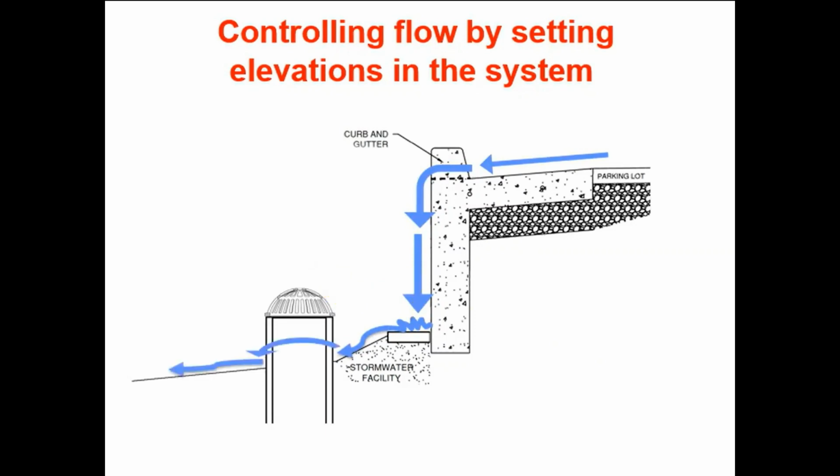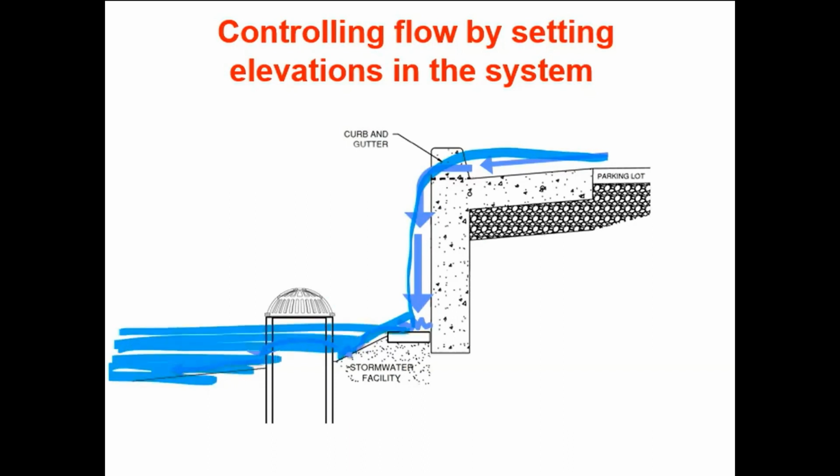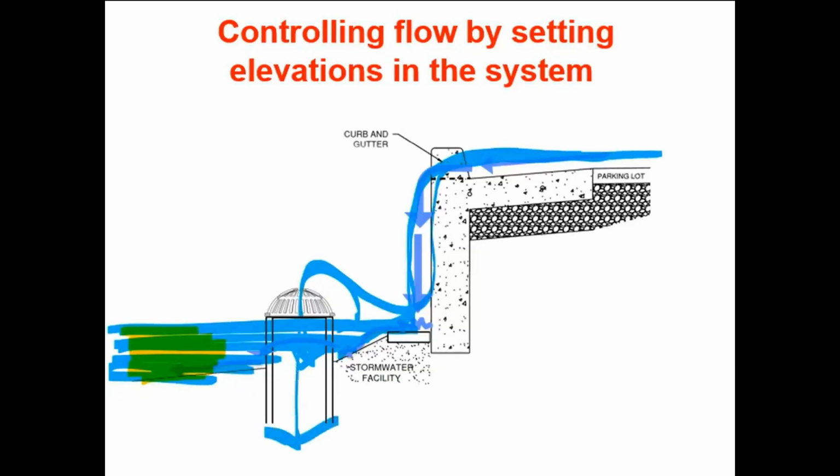The reason we want it at the top of the bioretention system is we want water to come down, hit the edge of the raised drop inlet. It's simply then going to go around the drop inlet. At that point, it's going to start to fill up with water. But because it is at the top of the bioretention system, any other water that comes in will go into the raised drop inlet. And so the polluted water that's down here is not resuspended into the raised drop inlet. It's only the clean water that comes in later in the system that goes down into the raised drop inlet.